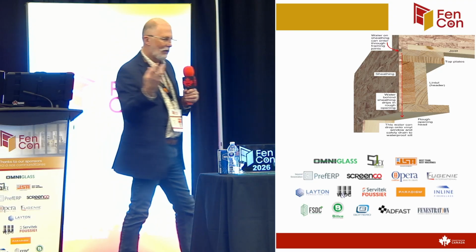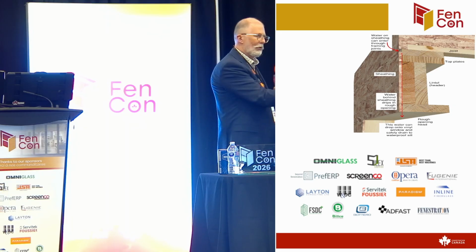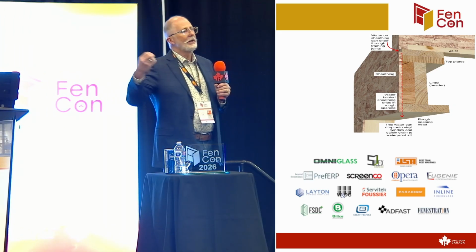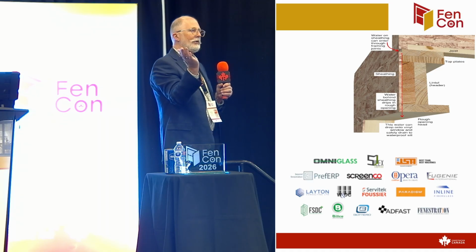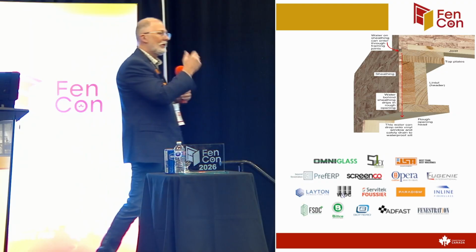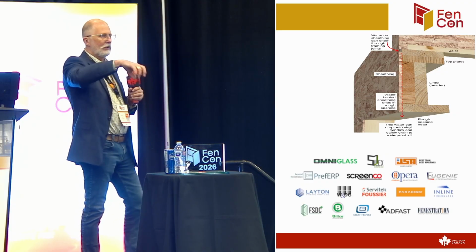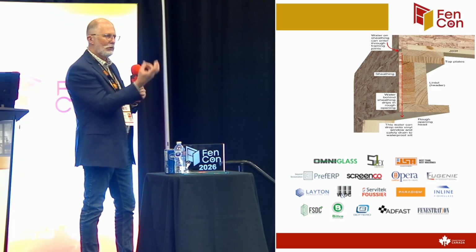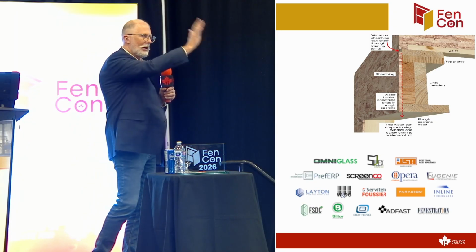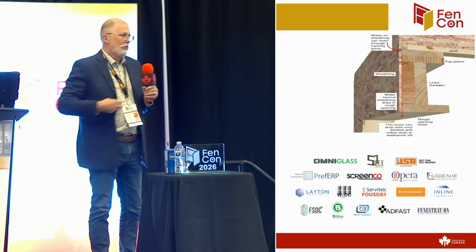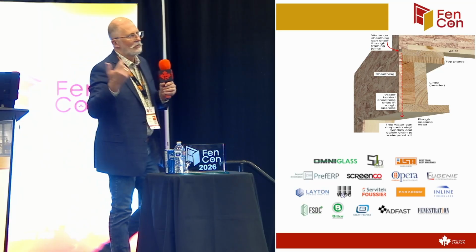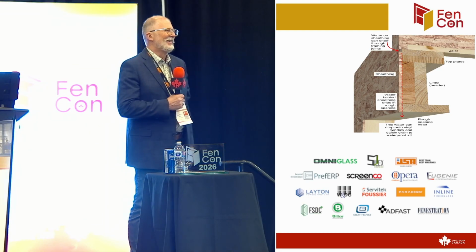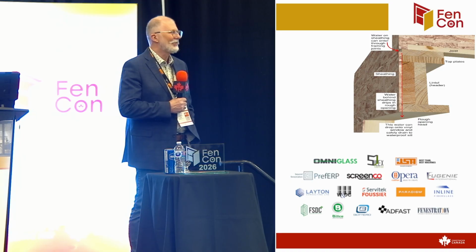So first of all, that air moving towards that location can absorb whatever moisture is there, but the more important thing is it displaces the air that's out there and pushes it out of the way. Depending on your mechanical system, we've done houses where we put little grills that come up through the interior double wall, that would shower the window with air, because they wanted an energy efficient house but also wanted 17-foot aluminum windows. The worst thing you can do on a really cold day is close your drapes and your blinds. Yes, absolutely.